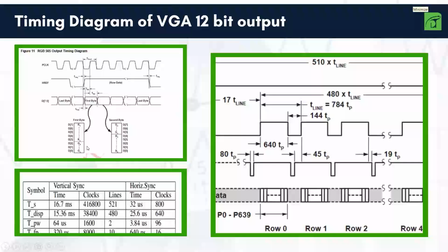So this is how the pixel clock and the RGB565 output format are completed from our end. The pixel clock, what we see here, has been generated as an input to our RTL. For the I2C settings, it generates a clock for us. Based on this clock, we take the reference, the H sync and the H reference are completed. The row pixels, what you see, are practically the pixel address we are trying to configure. The 8-bit data output latch, the first bit and last bit, are generated for my output format.